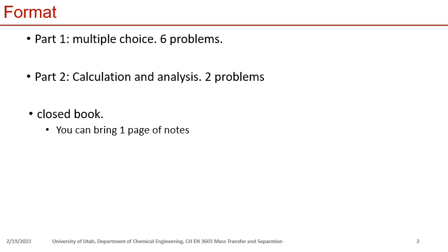And its own velocity can be broken down into two parts. It's made of the average velocity of the mixture plus a difference, like the relative motion of the species relative to the bulk fluid flow, and that's the molecular diffusion, right? So if you multiply this with each term in this bracket, you have C_A v_M plus C_A v_A,diff, right? And that's your convective flux, and that's your diffusive flux, right? And C_A can be written as x_A C v_M, right? So be very proficient at using this, because you will be using it to solve some of the problems.